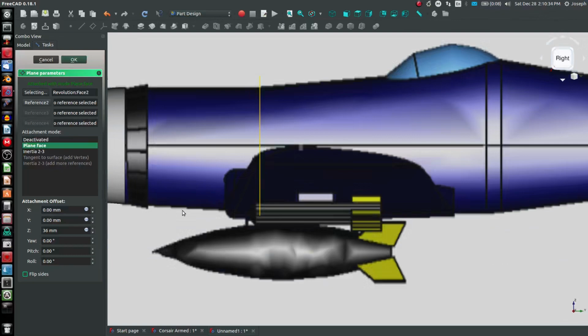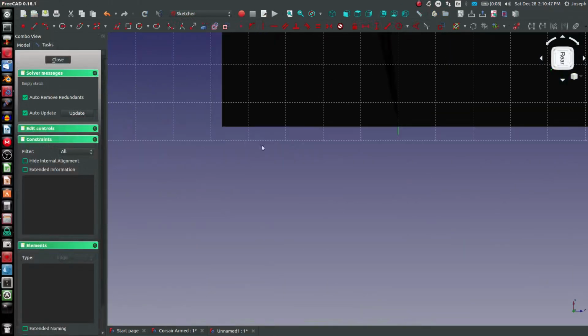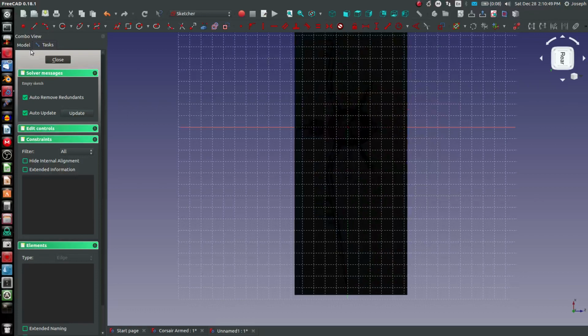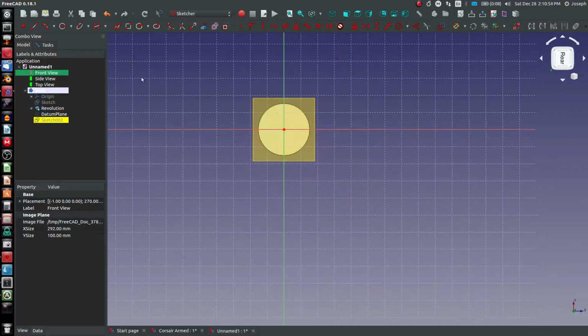The body also comes down here, so I think at this point the cross section of the body is going to be very nearly circular, but it won't be quite circular. It won't be exactly a circle. So highlighting this plane, we'll choose sketch, and notice we have a big plane in the way. So I'm going to select my front view and hide it with the space bar.